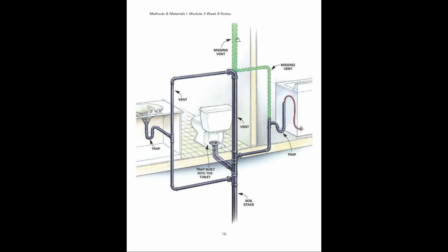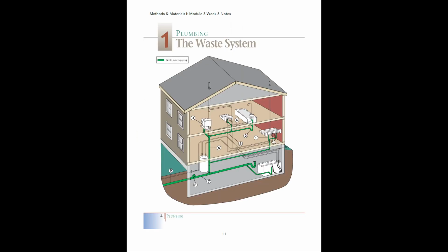We're going to talk about vent systems in a minute, but basically anything above the waste lines. So you can see this is the highest waste line in the stack here. We have another waste line here, one here, one here. Anything above the highest waste line is going to be considered a vent, okay? Another term for that is a vent stack, but we're going to talk about what that is in a minute. I just wanted to show it to you here while we're looking at this diagram.